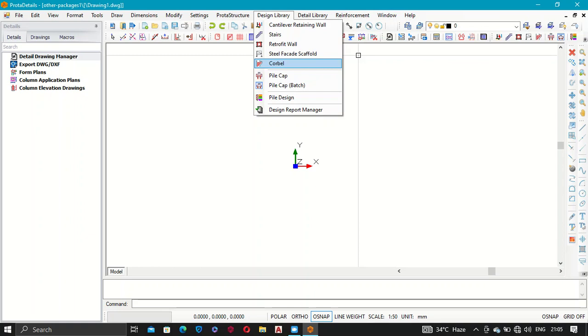Don't forget that the load coming there is moving away from the normal axis from the ground floor. So it's going to increase a whole lot of bending and shear at that point. So the corbel will help to limit the effect of that moment by increasing the section of that column at that point. You understand me? So that is that. So we also have pile cap.